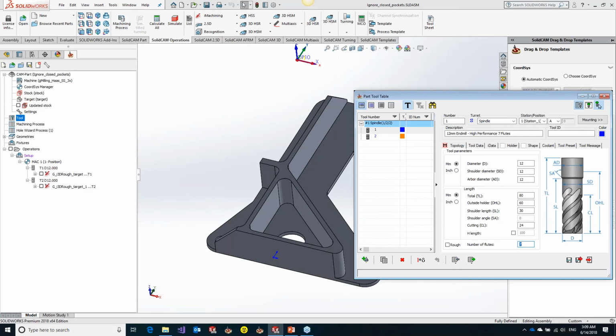The downside to this is if you have one of these high performance end mills, they usually aren't very good at helical entry. You may even get a statement from the tool manufacturer that helical entry or helical ramping is not allowed at all. So how do you deal with that in iMachining? I'm going to show how simple this is now.